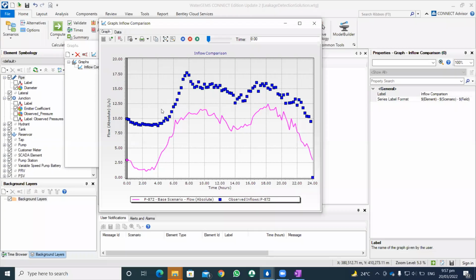Basically, when you design a water supply network, at the start when you operate it, the demand on the reservoir is less, and this depends upon your extended period simulation. From 6 a.m. to 12 p.m. the demand is high, and similarly, following the specific patterns you have assigned to each node, the water is drawn from the reservoir throughout the day based on that specific demand.